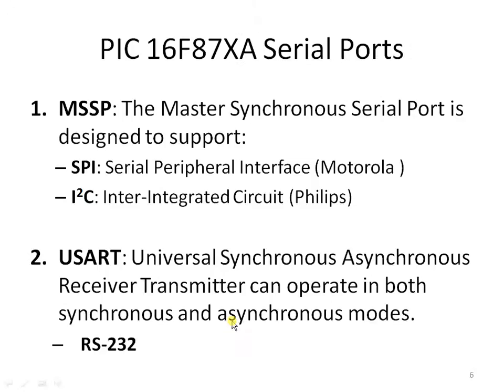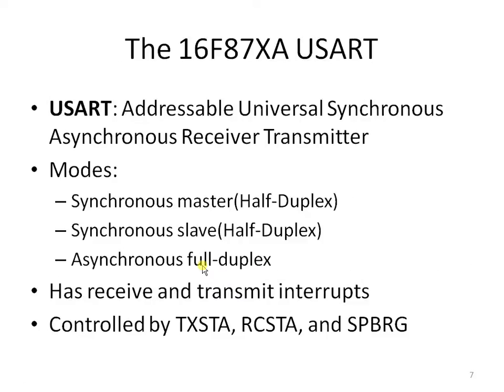Now if we talk about the peripherals inside this PIC, we have two serial ports. One is MSSP and the other one is USART. MSSP provides us two protocols like I2C and SPI, and these two protocols come under synchronous serial protocols. Now we are talking about USART. It provides only one kind of protocol, that is RS232. So let us see this USART in detail.